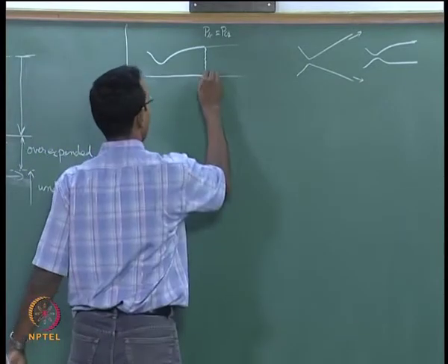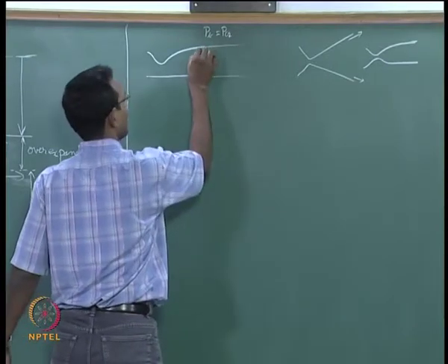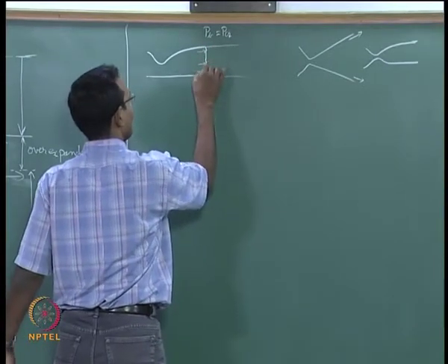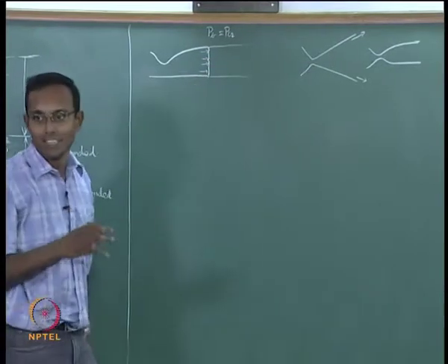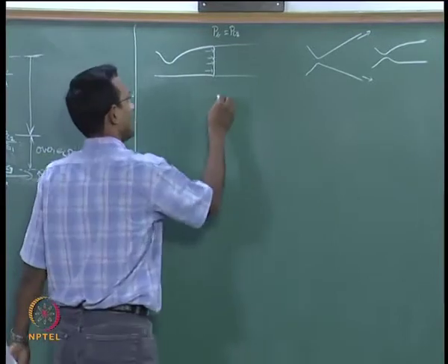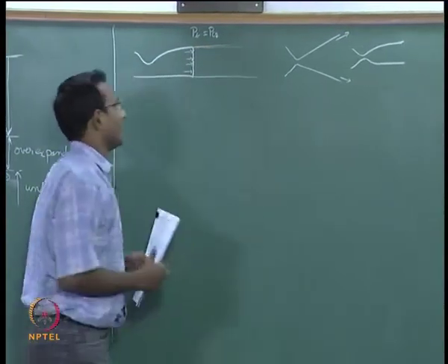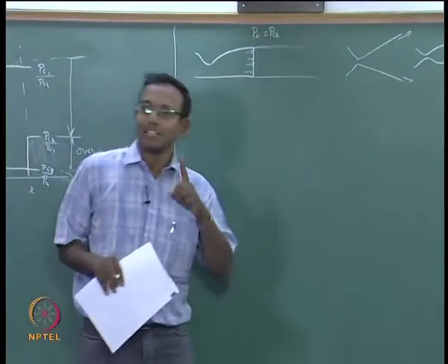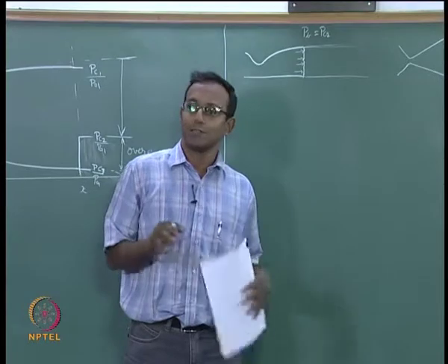We are solving only 1D gas dynamics as of now. So, my jet is going to be just parallel to whatever is incoming, except for before the shock it is supersonic and after the shock it is subsonic, exactly same mass flow rate that you know, and so it just goes out as a straight jet. And we assumed one more special thing, we are in inviscid gas dynamics.